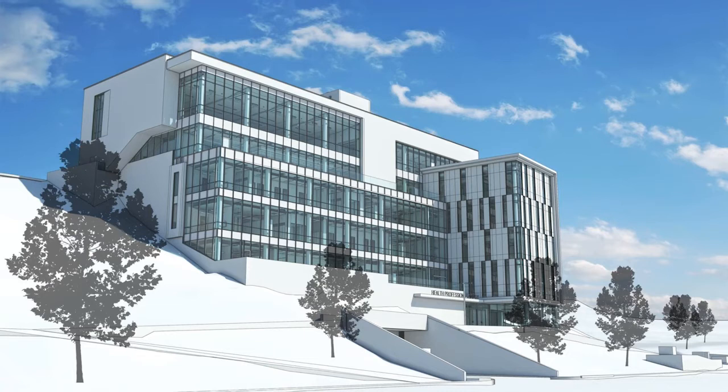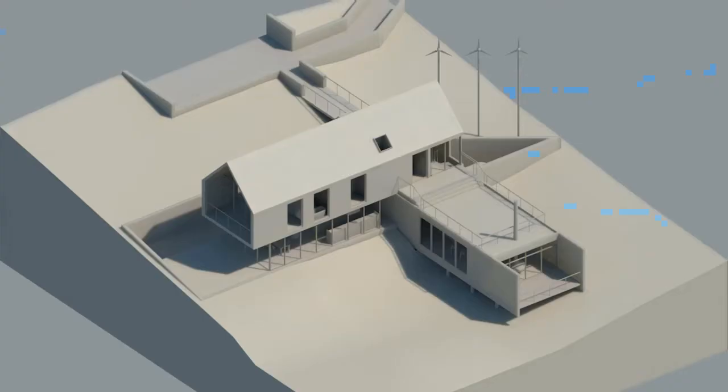But we want to look at this. We also want to look at taking this a step further. And so this is an example of a 3D rendering of the exact same model. This is a 3D view from the Revit sample scene that everybody knows and either loves or hates, depending on how you look at it. We're using a subsurface scattering material, an SSS2 material here, to get a look of a 3D printed model.